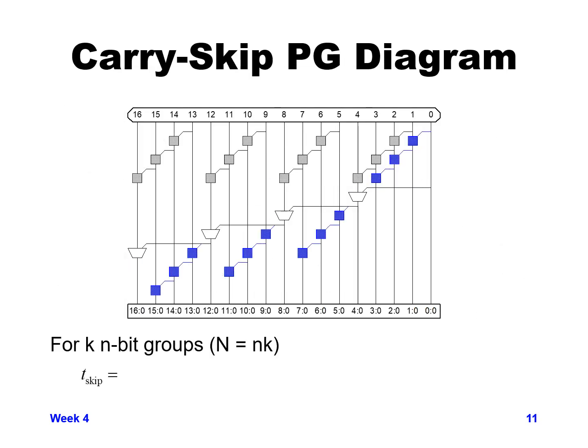So now let's look pictorially at the carry skip adder delay diagram that we were talking about in the previous slide from a logical point of view. Let's say we have k number of groups that have n bits each in their group, and our total number of bits, capital N, is equal to small case n times k. In what we had in the previous foil, we have 4 groups of 4 bits each. So both k and n are 4.